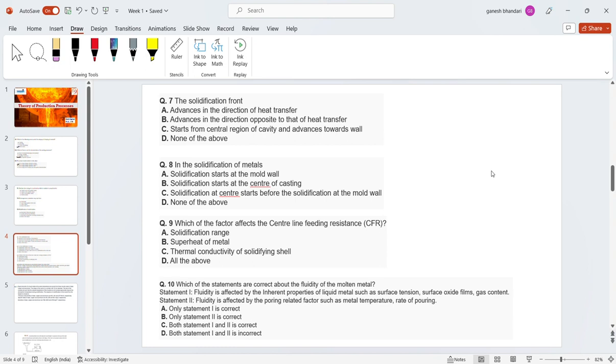As your melt is flowing from left to right, the solidification front means its state is changing from liquid to solid. As your heat is transferred from left to right, because here the heat was higher and there it is lower, firstly the solidification will start the moment it touches the pipe. Then only it will travel more. So they are in opposite direction. Have you imagined what I'm trying to say?